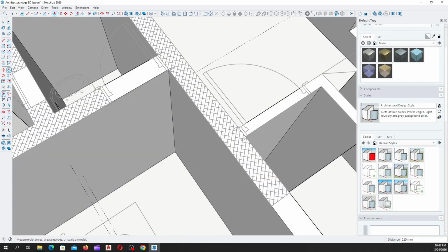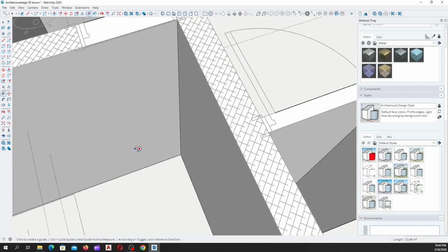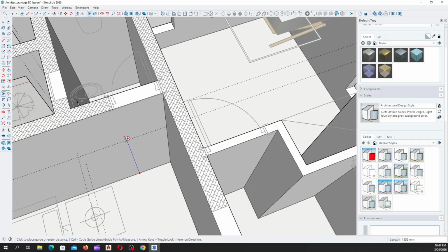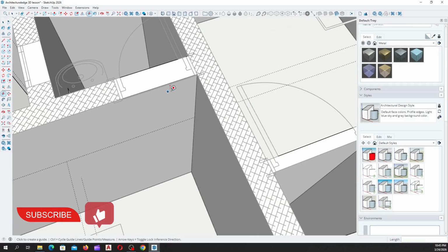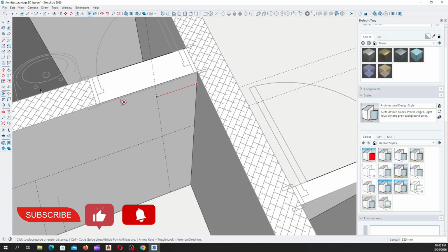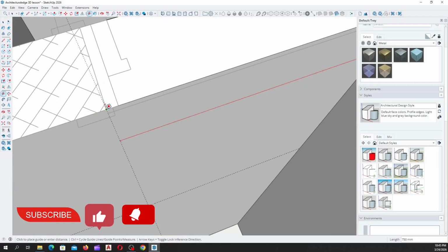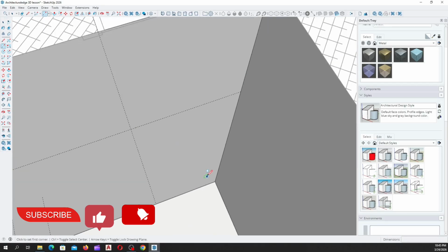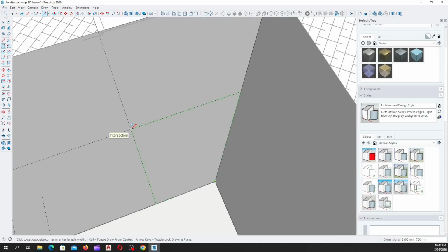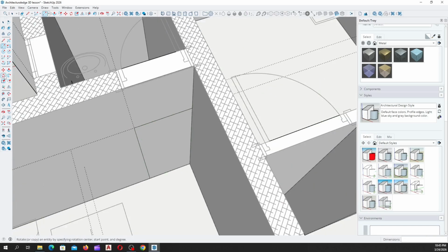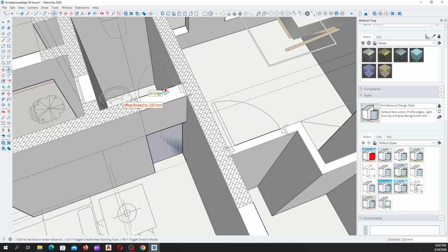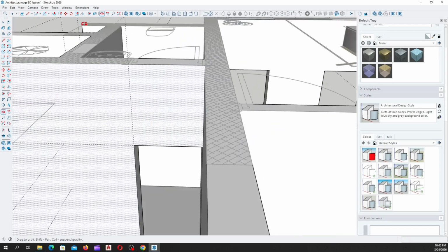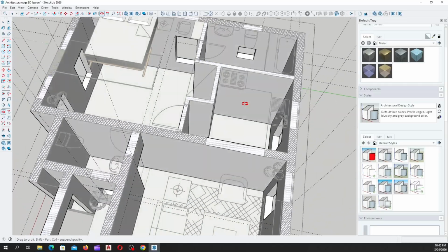All right, so let's move into the interior spaces of our model. So we'll be creating our interior door openings. So we'll offset the value 2100 millimeters. Then we pick from this edge. Then we snap it here at this point, which is for our visitor's toilet door. Okay, then we'll pick our right angle tool and do this. Then we'll push in and snap here. You see, our door has been created for our visitor's toilet.